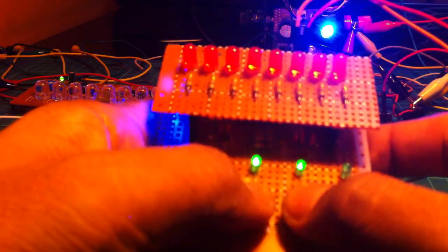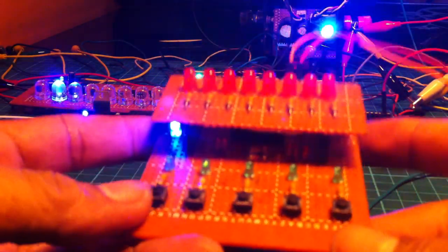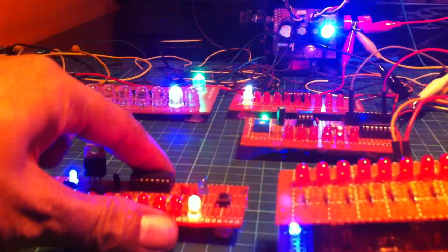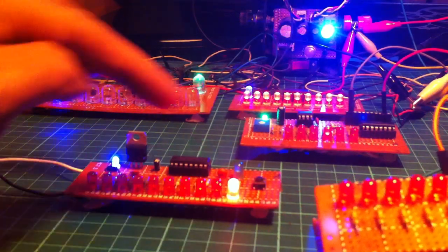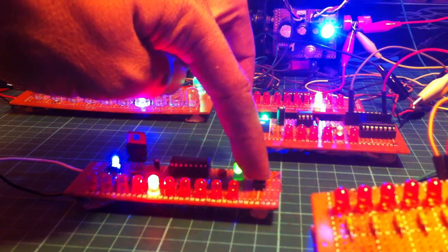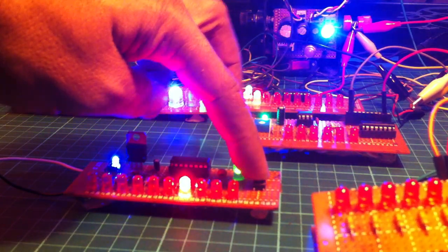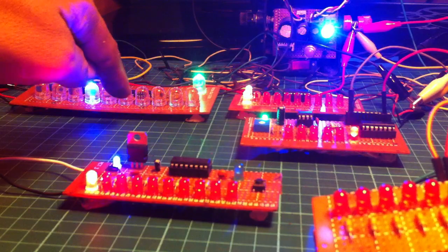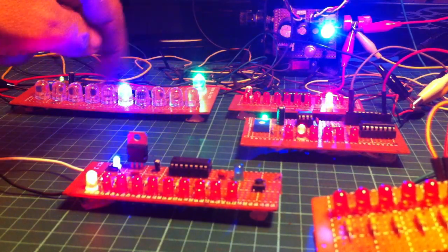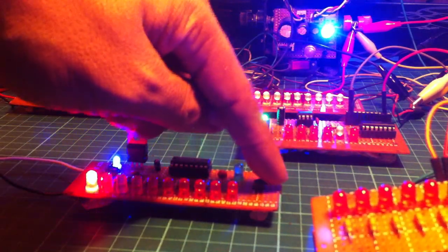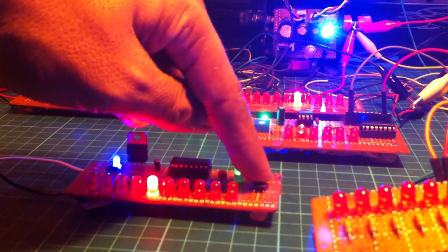Okay, clear again. The difference with this one, with what we have here, this is the only manual counter. This is a shift register. We have this manual counter using the 4017, when you press the button here, the LED tends to shift from right to left. Just like that one. That one is an automatic counter because the clock is provided by the 555 timer. The clock here is provided by the push button.